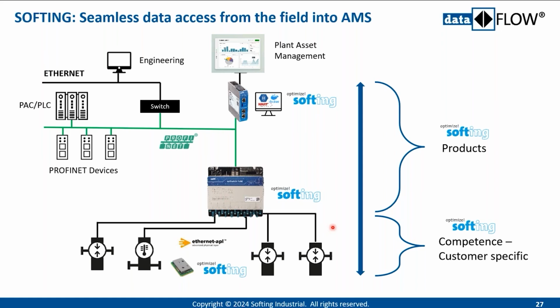Again, I think we had the question earlier, but from Patrick Valasovic, is your field APL switch Ex rated? So Ex certification, basically. Yeah, it's ATEX. So it's zone 2, so it fulfills all the zone 2 requirements for ATEX. Perfect. I think we are sharing this slide deck anyway later on, because on one of the slides we have all the different ATEX specifics on it.